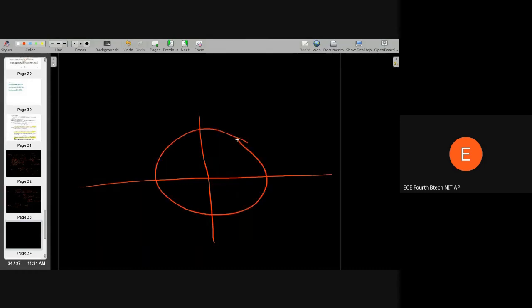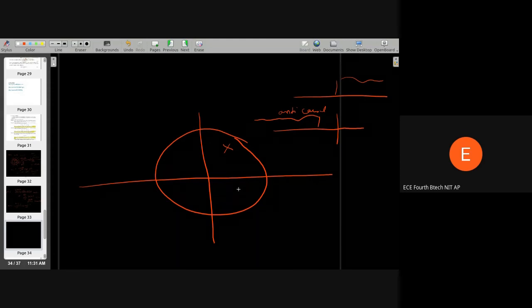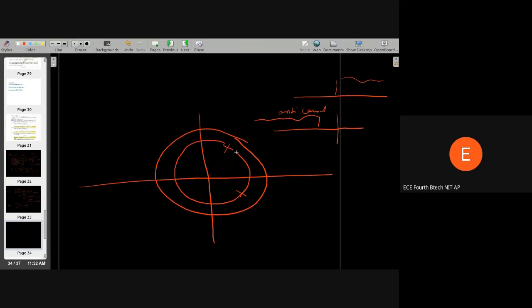This is your unit circle. Now, just as a signal can be right-handed, it could also be a left-handed signal or anti-causal. It's also called anti-causal or non-causal. And let's say your poles are here inside the unit circle. So your ROC, ROC never includes the poles, but it will be inwards, excepting z equal to 0, that you have to check.